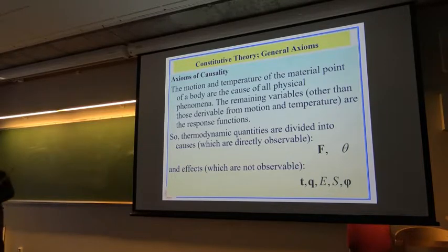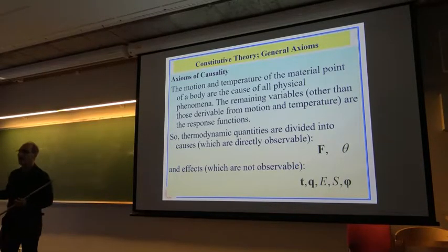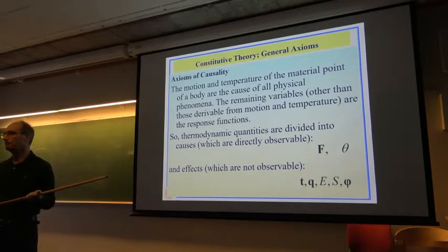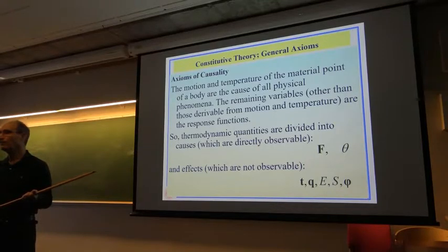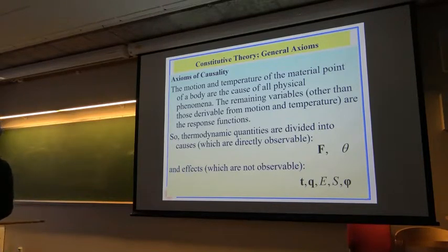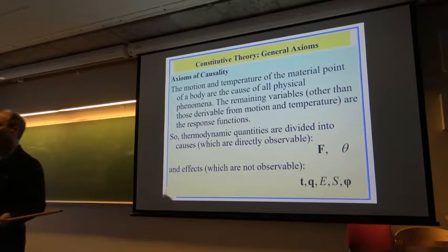Just a question, in the case of an equilibrium system, so then no motion, you say temperature determines material properties, and as an effect you have the stress tensor, which would then become the pressure, I assume. Is the pressure? I mean, because you have three thermodynamic variables typically, so you can fix temperature, pressure, and then you fix the volume. So it would seem that that's an independent variable. No, but pressure, they are related by means of the equation of state. Exactly, you have equation of state.